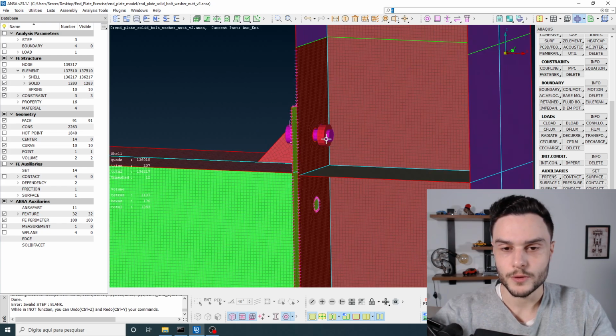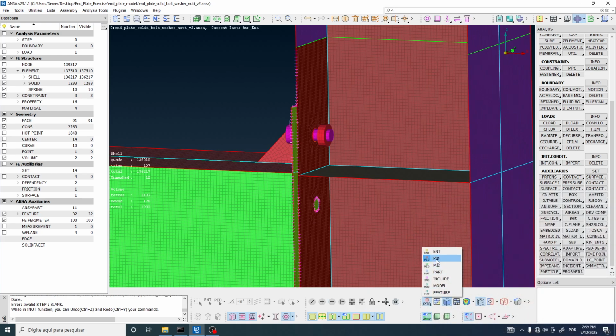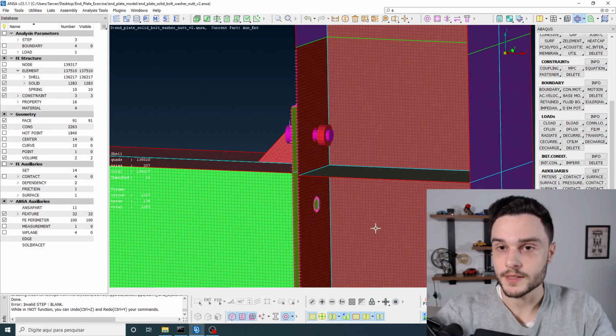Okay, so first of all, just to be sure that you have the same visualization setup as I have, choose Abaqus deck here, and in the database we can deactivate visualization of curve and point, and in the pink buttons you should have everything that I have activated here, and also for the yellow buttons in here deactivate the spots and hard points, and in the draw mode select property ID, and that's it.